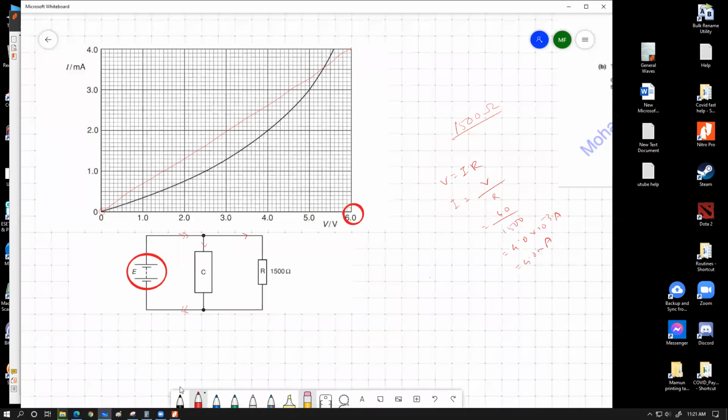Have a look. Whenever the voltage supply is 2 volt, this element C is going to be pulling this much current from the battery. So we have to plot this graph all the way up over here, and we get about here, which is nearly 7.5 divisions over here. I can write this as 0.75 milliampere. And if you draw this graph carefully with a straight line, you should also get a perfectly fixed number as you come up over here.